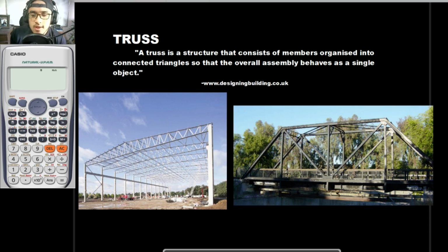Suppose that a certain car passes through this bridge, and let's say that the car weighs about 2,500 kilograms. Of course, if the car passes through here, its weight would be transferred to the flooring. The use of this truss is to distribute the load of the car to each of these structural members. And those forces are what we call bar forces.